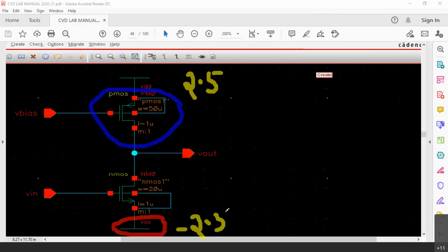You would have used such VCC and VEE when you worked with op-amps. Operational amplifiers can be used with the single supply also. They can be used with the dual supply also. Now what is the advantage of using the dual supply when compared to the single supply? In the case of a single supply, the output of the amplifier should be kept at half of supply voltage.